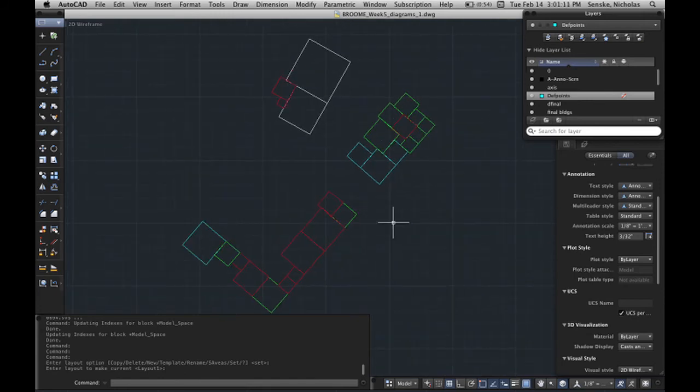Offhand, do you know a good stroke for a 1/16 drawing? For a 1/16 drawing, I think what might help is just to try different weights. Go into Illustrator and make a 36-inch by 12-inch strip, and then draw like 20 lines, set them to different weights. 20 is arbitrary. Set them to different colors, so grays, reds, black. Print them off on the school printer, just that one strip, so 75 cents or whatever, and then that's your reference, right? And then you know what that is.